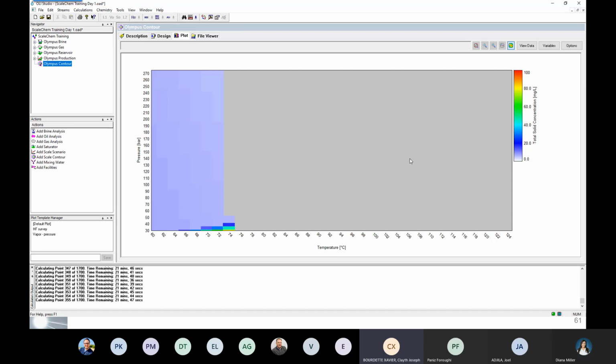So that was really an interesting tool to see how I can first calculate the corrosion rate based on the pipe wall thickness and the different flow and temperature cases that I have, and import it to see if it's predicting in line with the last inspection result regarding my corrosion rate allowance and then the design year life of my pipeline.